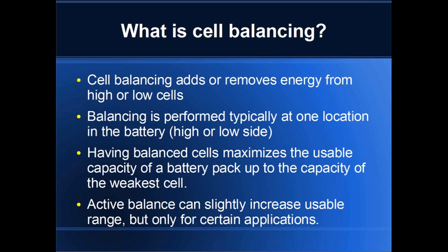And chances are somebody's not going to take the cell phone or the drill battery or the car off the charger the moment it hits the top every time. And that gives you more time to balance. If you're using a resistor or some type of dissipative balancing, it means that you can go with a smaller balancing circuit, reducing costs. Not every application works like that.